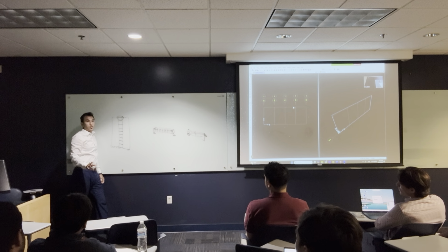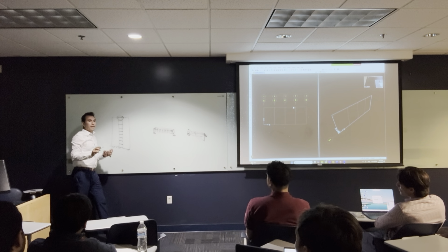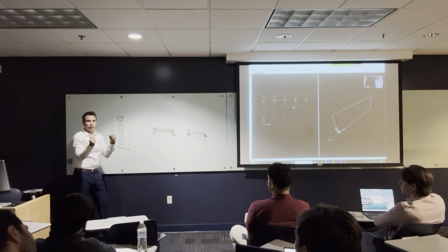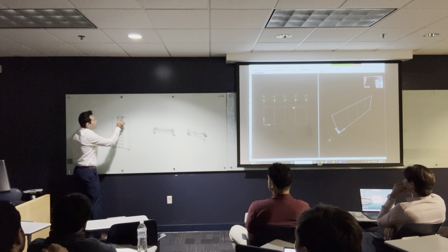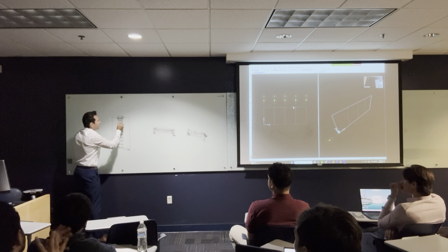It's a very, very special beam. If you model this beam as a frame element, you are not going to see what this beam is actually doing. Basically, the two walls are not going to feel this beam. So what we did, we made it a shell element. It was something like this. We modeled the whole depth of the beam, something like this.